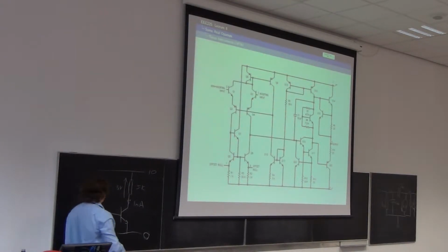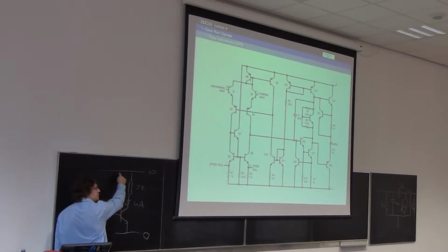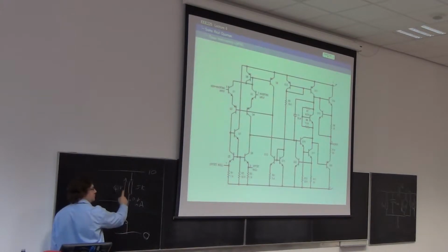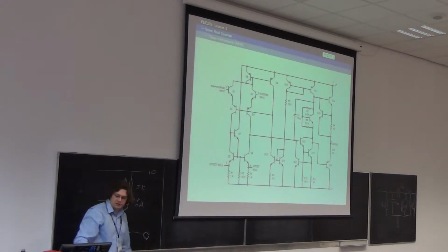Yeah? If I turn off this transistor a bit, this current should fall, and if that current falls, this voltage will fall. And if this voltage falls, the node voltage on that node has to go up, because it has to get closer to 10. This goes down to 4, because that goes down to 0.8 milliamps, then this node voltage has gone up to 6, 10 less 4. That's why it has to go up. Happy?